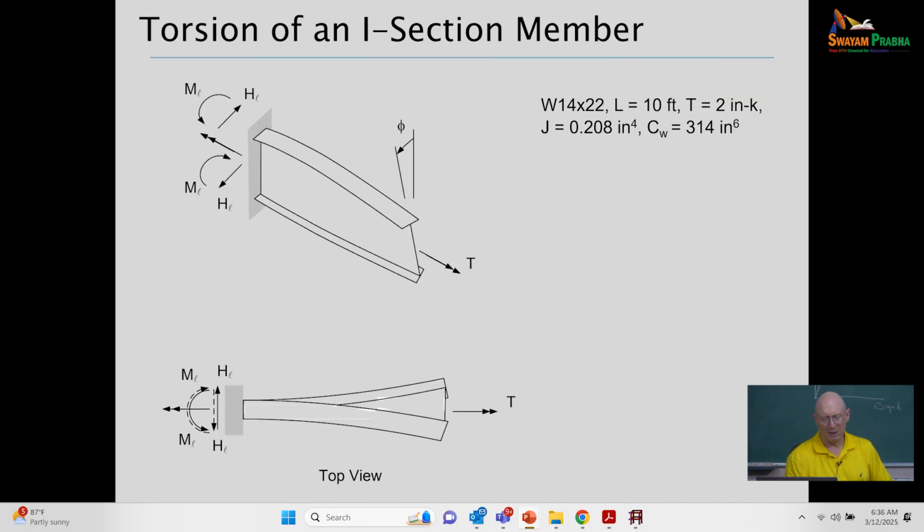And so what's the importance of that? This is a little first order analysis example to try to highlight the importance of that 7th degree of freedom at each node, which basically allows us to model warping in the frame solutions.